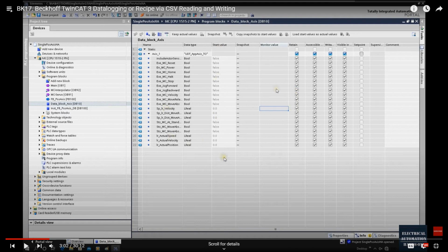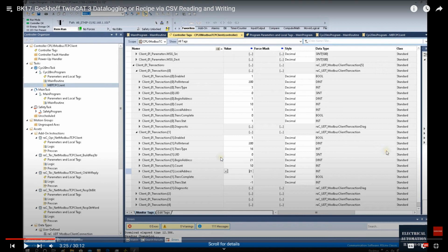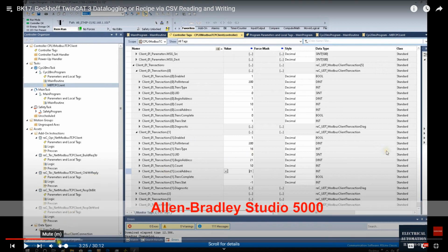This is the Siemens TIA Portal system. And for the Allen Bradley system, it is also quite straightforward. In this picture, at video 330, while you are online with this controller using Studio 5000, once you click save, all the values that were online will be captured and saved in this value column. Then they will be stored here. If you go offline with the project, you can still see all those captured values.